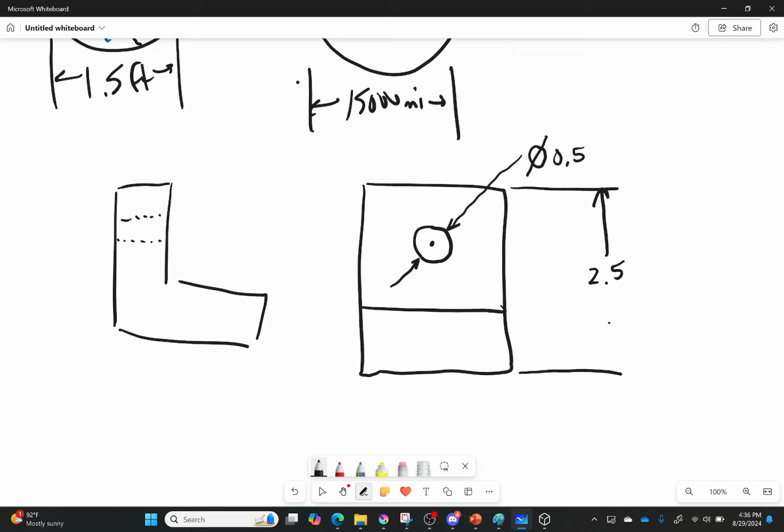Is it really? I don't know. And then I'm going to add the height of this bottom piece. Now, when you have a smaller dimension that is parallel to another dimension in that same view, you always want to put it on the inside. It just looks a lot nicer and people will not hate you. So, looks like that. That's going pretty good.